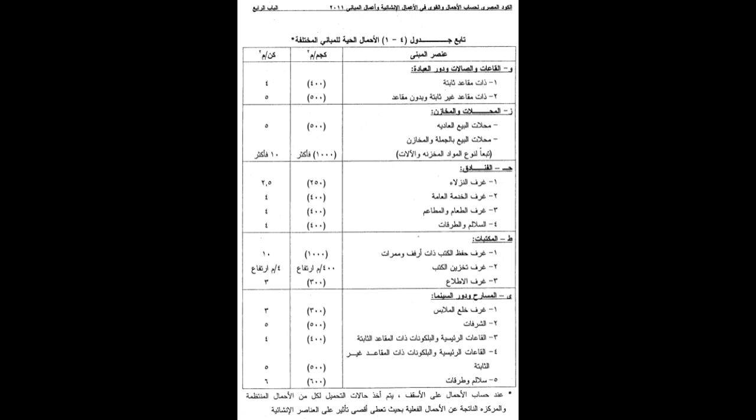For cinema, rooms for exchange 300 kilogram per square meter. Balcony 500 kilograms per square meter. The main halls and balconies with fixed seatings, 400 kilogram per square meter. The main halls and balconies where the seats are not fixed, 500 kilogram per square meter. The corridor and the stairs, 500 kilogram per square meter.